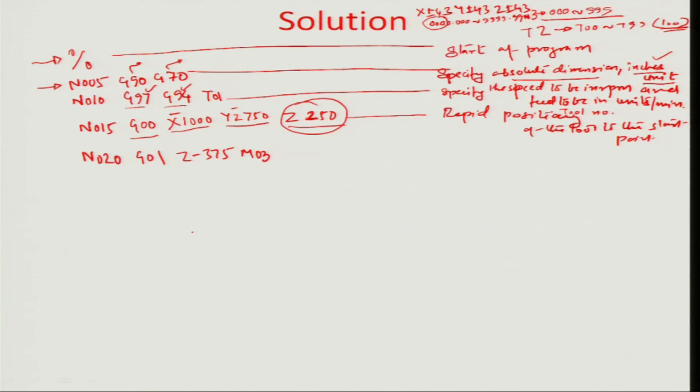You can also give a speed at this particular point to the rotating tool. The speed was given to be 500 RPM. Obviously the RPM mode has been described earlier, as you can see by the code G97. So we are left with S500, which is the speed of the tool.